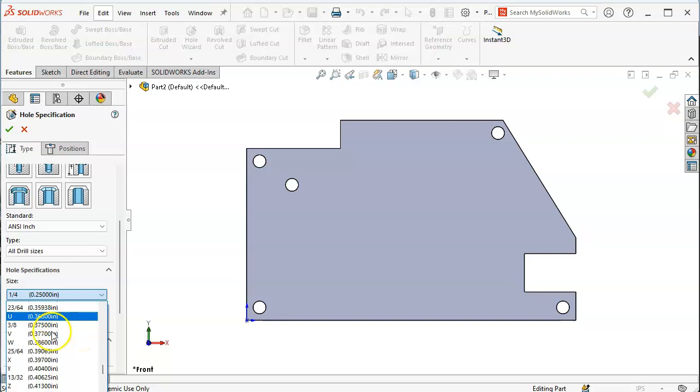So way back when we study ancient history, like the 1800s or so, when they went through and did kind of an analysis of the standard, rather than having a drill size every 10 thousandths or every 5 thousandths, there were basic clearances, and it was kind of a statistical analysis that said, hey, these are going to be letter drills, these are going to be machine drills, and we get close, but in the case of a 0.4 with a standard 2 decimal place tolerance, depending on the industry, would say plus or minus 10, sometimes up to plus or minus 30.